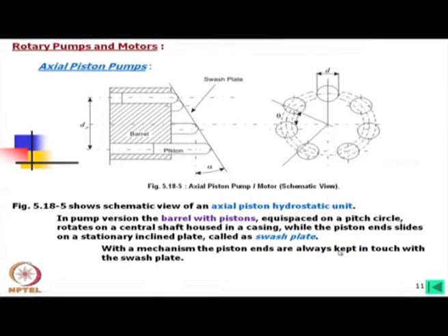There is no guarantee with this. Although when a little suction head is generated, the oil is coming in. So, whatever small pressure it may be, still the piston can move, but to guarantee that the piston ends are always in touch with the swash plate, a separate carrier is fixed with the piston.